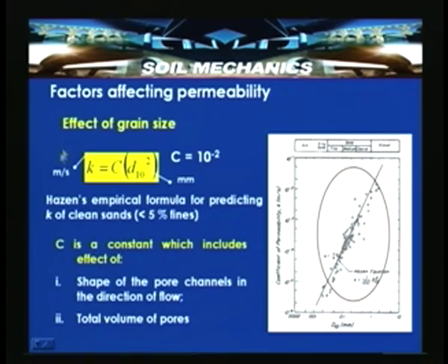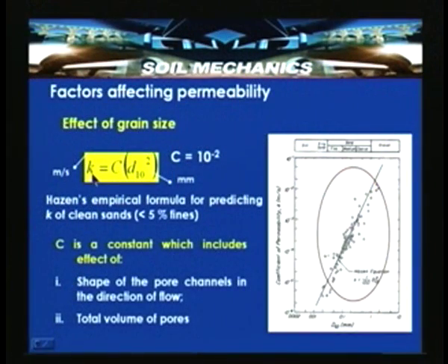So, this is a very important equation for determining the coefficient of permeability based on the particle size distribution. This is one of the significances of the particle size distribution we discussed while discussing sieve analysis of soils. Here Hazen's empirical relationship is shown, which is nothing but k is equal to C D10 square, where C is a constant obtained from this regression. The zone circled and highlighted here shows silt and sandy particles. This is where the large number of sample points are.